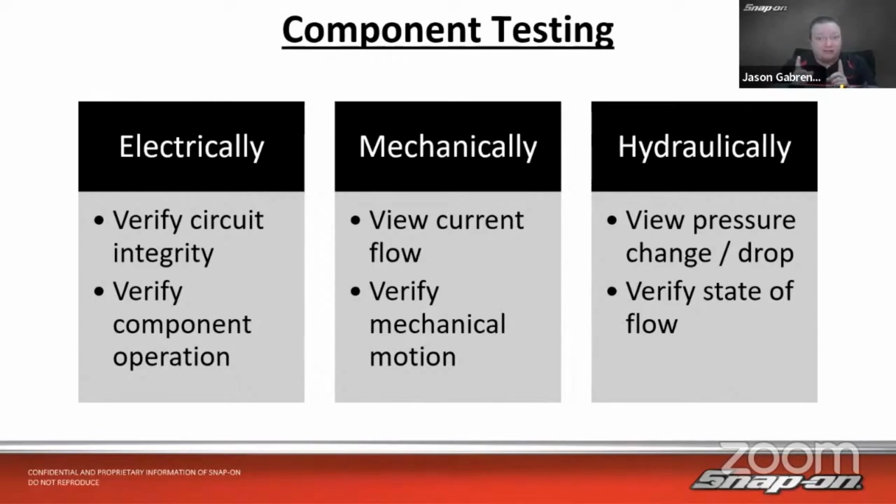If I see that the injector is commanded open, right? So I see my pattern on the injector, and my pressure doesn't move, then that injector really didn't open. Maybe mechanically it opened, but it didn't spray any fuel, right? We can see that. We can see how it drops off. And if it drops off excessively, that could be another problem entirely. Or if we see that it doesn't build up the proper pressure, maybe it's not closing all the way, it's leaking, right? So we can see all these different things by being able to compare.